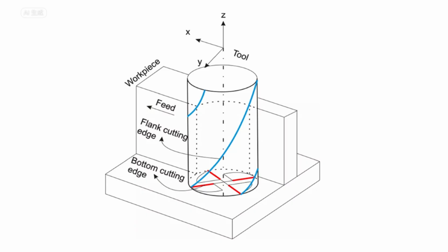Machine setup. The end milling cutter is secured in the spindle collet or tool holder, whereas the vise clamps or fixtures hold the workpiece. Consequently, the position of the workpiece is parallel to the table or the spindle axis. The value of the input parameters depends on the working materials and tools' coatings. The operator sets the reference point, work offset, after setting tools and workpiece.